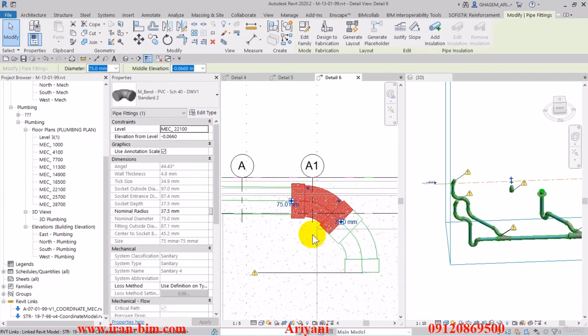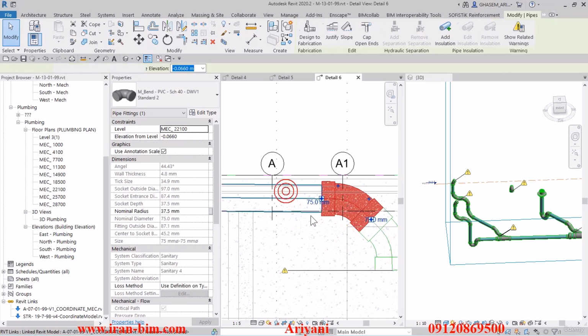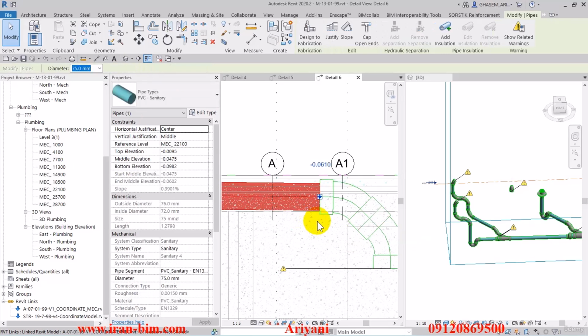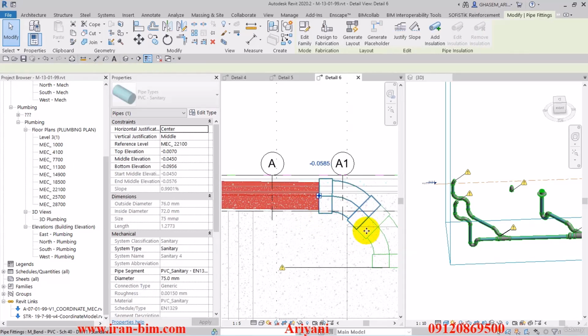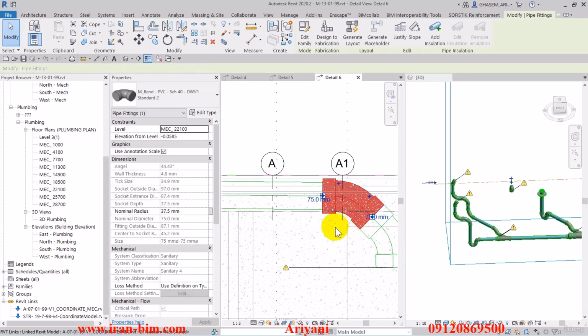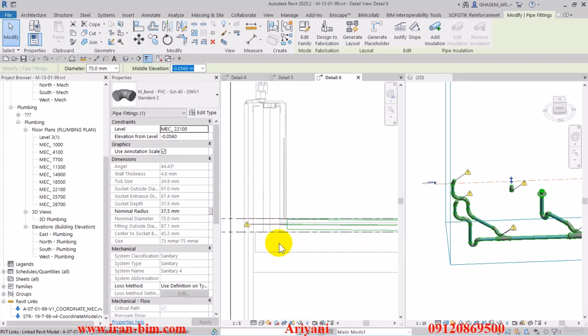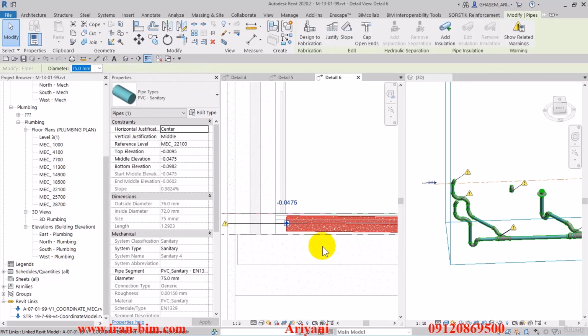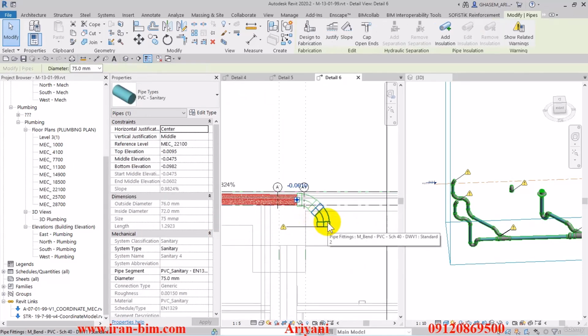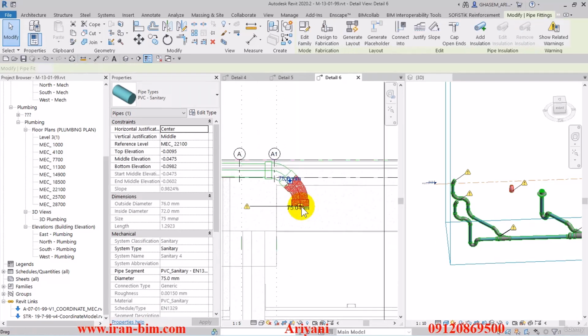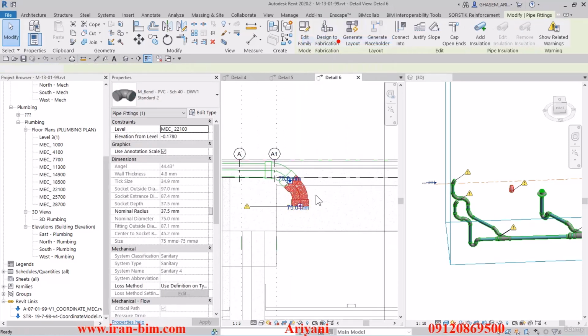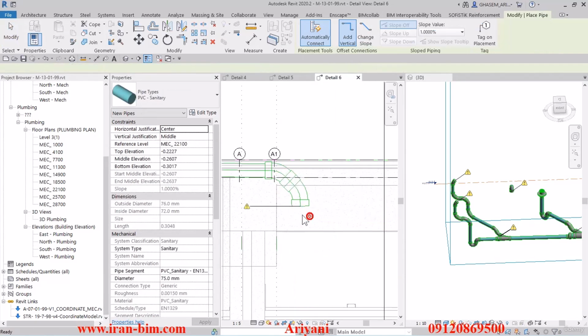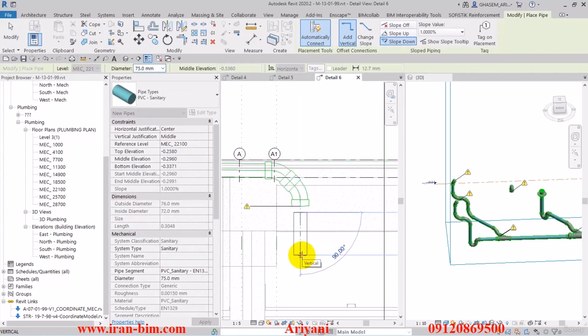Alright, let's just select it and move it towards the right direction so that it doesn't hit the beam itself. Just needs to move up as well. Alright, then move the fitting itself forward a bit, and there we go. So after that, I'll right click on the mirrored fitting and select the draw pipe option. Now using this, we'll delete the fittings, but they will come back.